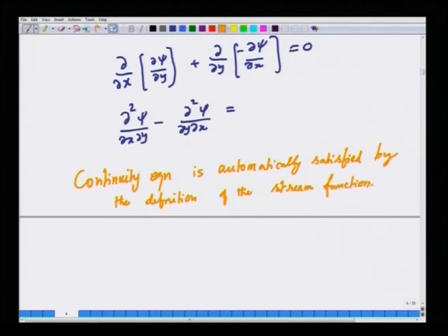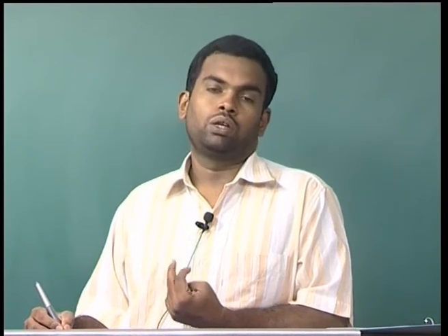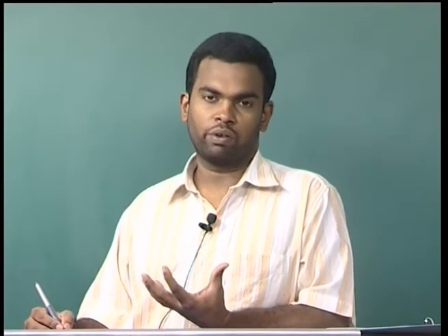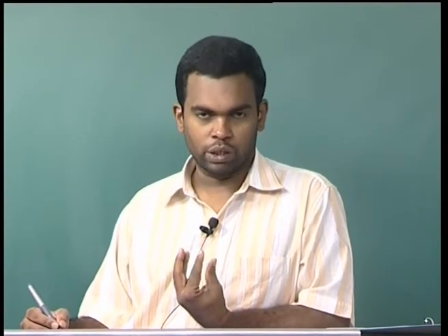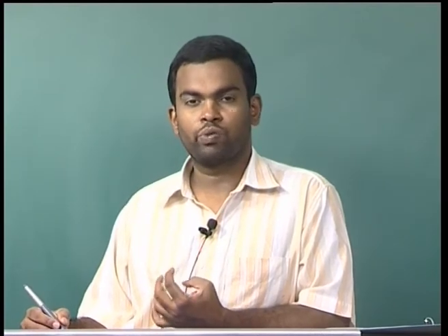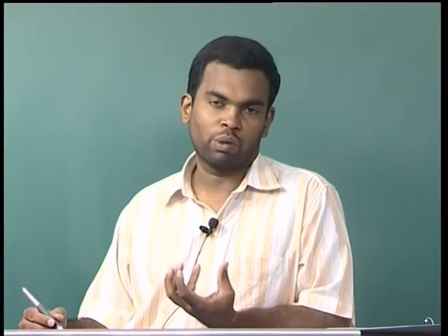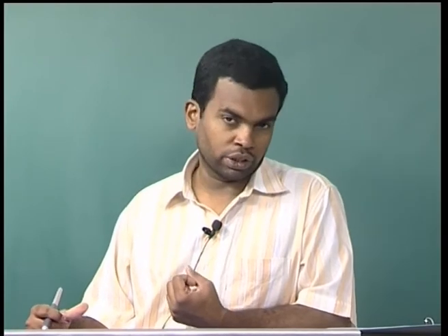This is a very important conclusion, because now we are finding that by defining the stream function in this fashion, you are automatically satisfying the continuity equation for two dimensional incompressible flows. That is a great simplification, because when you want to proceed further to momentum balance, you will find that you will have two sets of equations, the mass balance and momentum balance, which are coupled to each other.